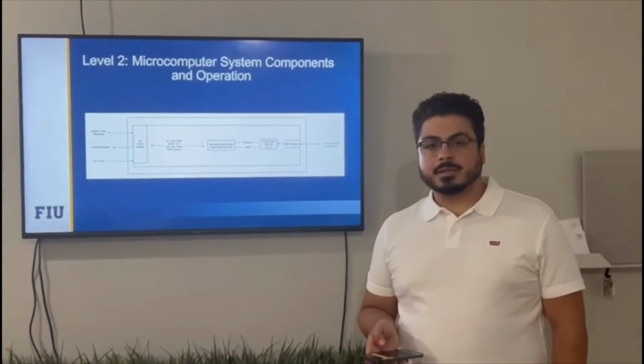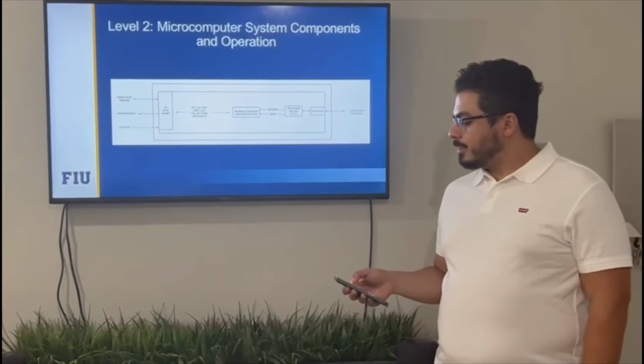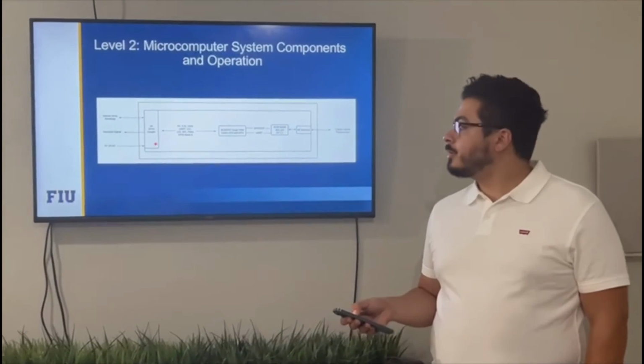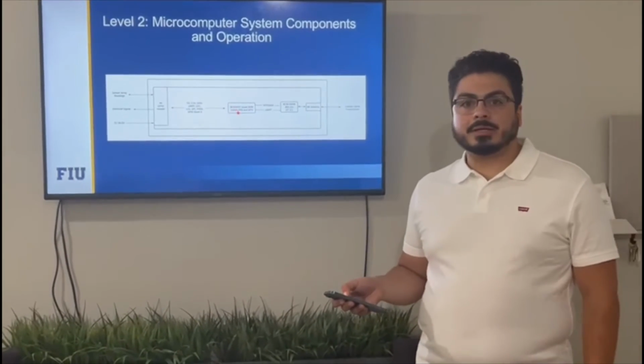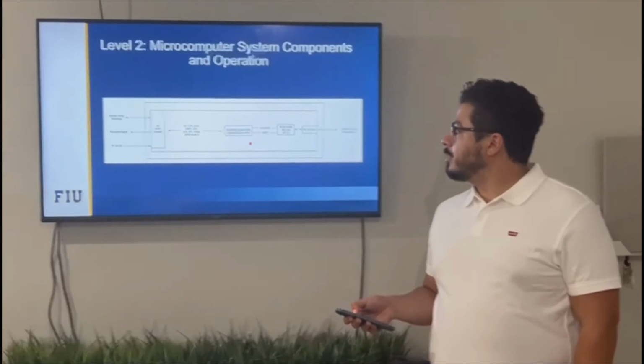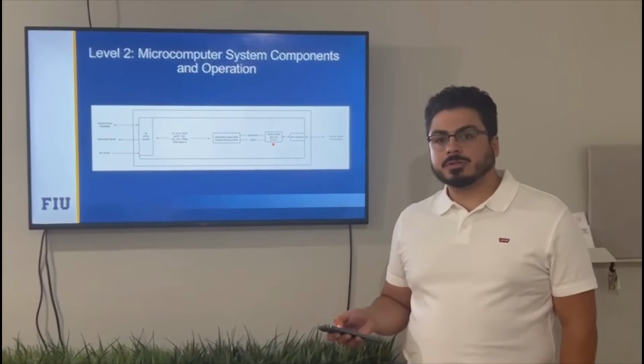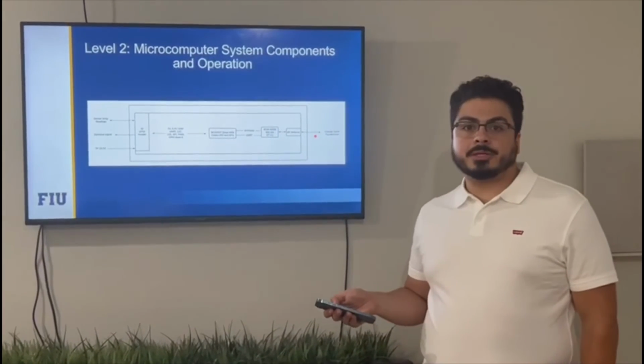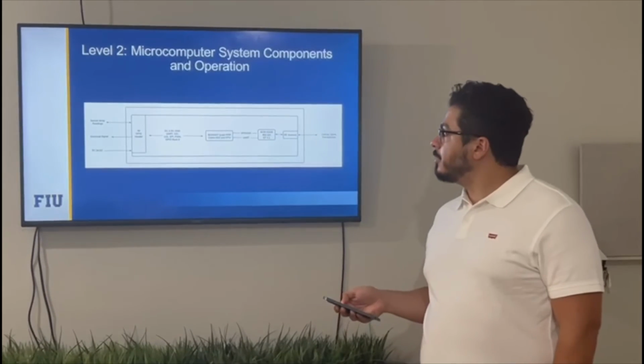We're then going to look at the level 2 of the microcomputer itself. It's going to take in those readings and that power generated through a GPIO header, which will then connect to the main processing unit on the chip. And then we're going to connect to the wireless portion of that chip, and using an RF antenna, we're going to create a cellular uplink through which that data is going to go out.